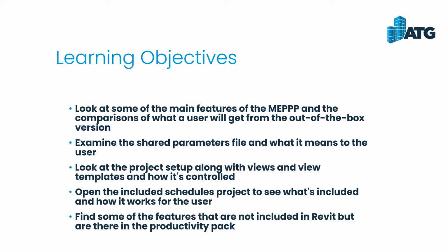Also utilizing view templates within a project. I really push view templates when I train users on Revit. I've done a previous webinar on specifically view templates alone, but that is a crucial part. And again, that can save you a lot of time on a project by getting well-created view templates and obviously setting them for the individual views that you go in and create.